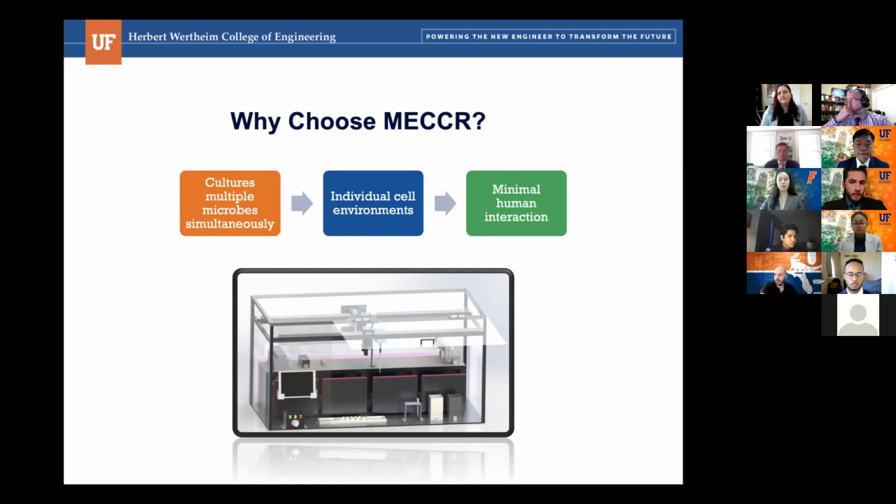Is there a better way that you can think of, where maybe you don't need quite such good positional tolerance on a pin system like that? I couldn't think of one, because the whole goal is to hold it in one exact spot and not have the drawer move. And to hold something exactly in a spot does require quite tight tolerances. I would suggest that a tapered pin would get you the same place with a lot less precision requirement on the initial positioning. That is a great idea. I did not think of that.